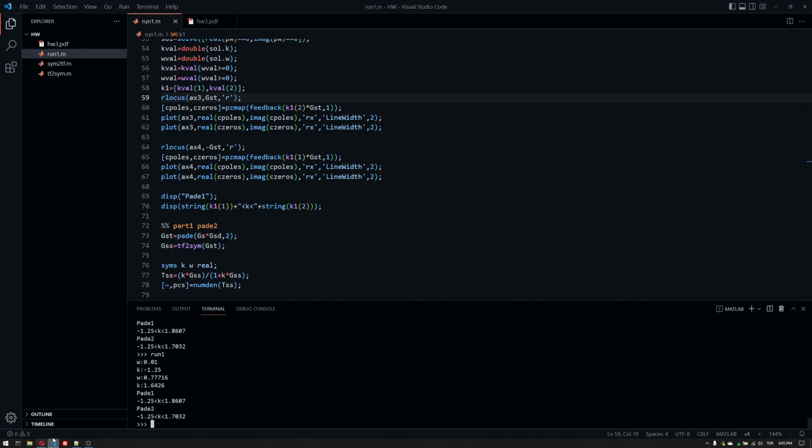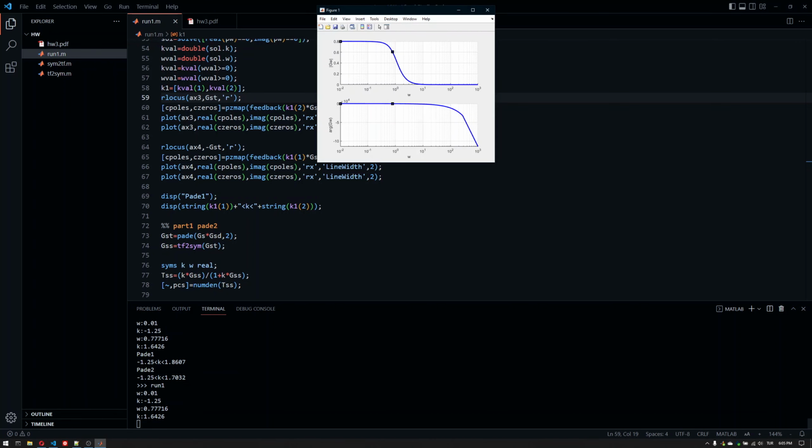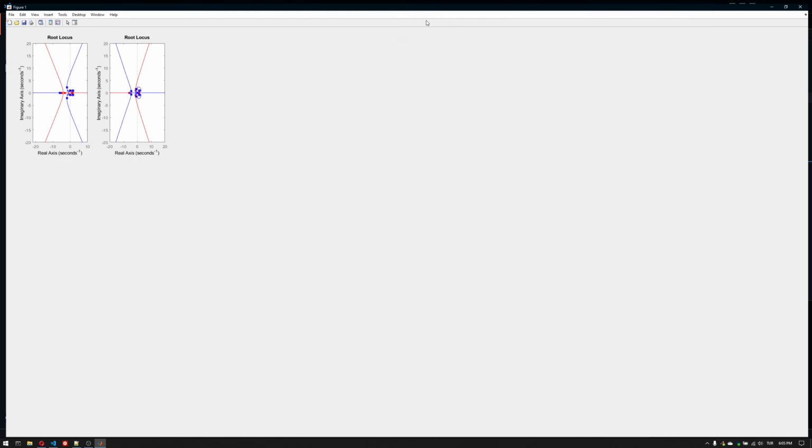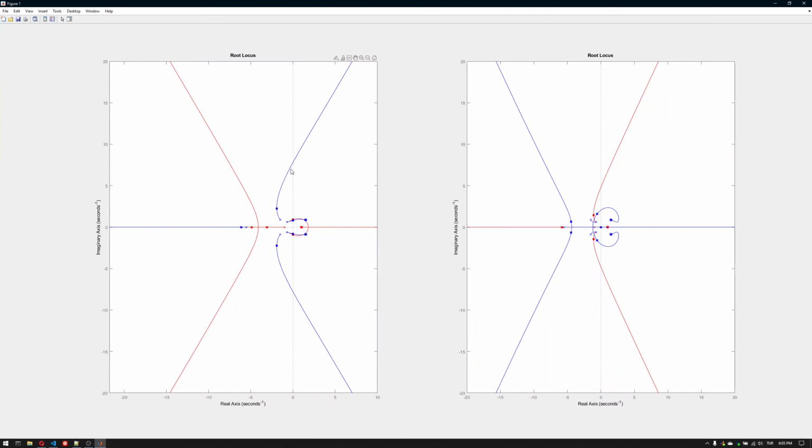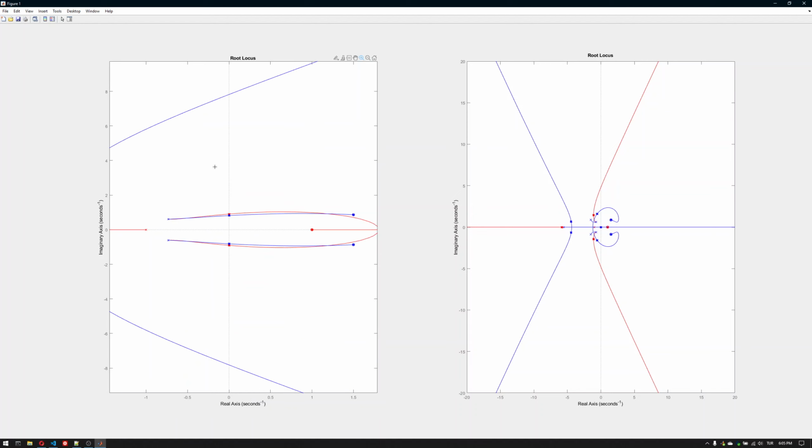But the system model, let me just show it again, the system model using the Padé approximation has some problems for the upper bound. And the reason behind that is the following. The system tries to model the root locus as close as possible to the actual system with delay. But the issue here is that it's capturing the wrong omega values here.